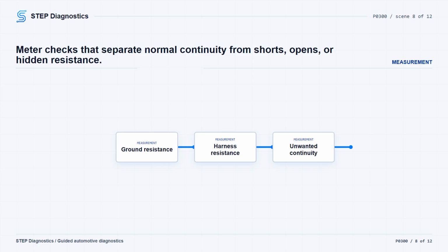A standard DMM ohmmeter's low resistance resolution, approximately 0.1 ohm, limits its accurate use to circuits carrying less than approximately 5 amperes. For unintended continuity, disconnect both ends of the circuit and measure between the suspect circuit and ground. Expect resistance greater than 10,000 ohms. Between two unpowered circuits, disconnect both ends of the two circuits, measure between the two circuits, and expect resistance greater than 10,000 ohms. And on voltage drop testing in general, expect less than 5% of circuit operating voltage.